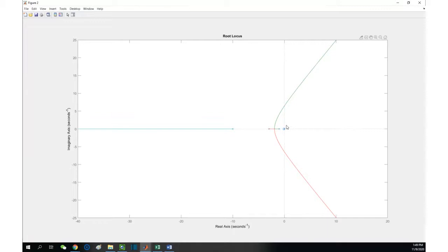Anyone has any idea how to design the Kp from here to keep the same zeta? How to find the Kp? Well, can't we just look on the complex poles to find 0.503 approximately, and then that'll be our gain? Go on. Wouldn't that be the gain then that we would have if we can find our point? Very good. Very good. Very good. Okay. I hope everyone is following. John was right.